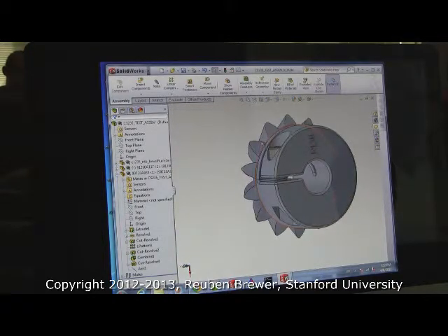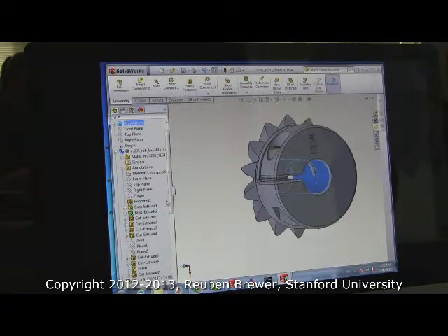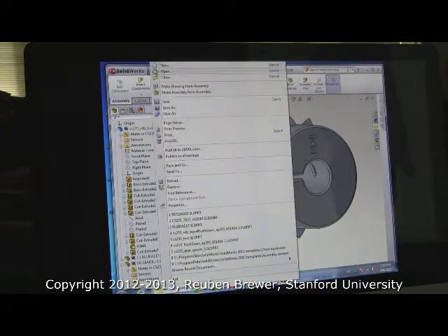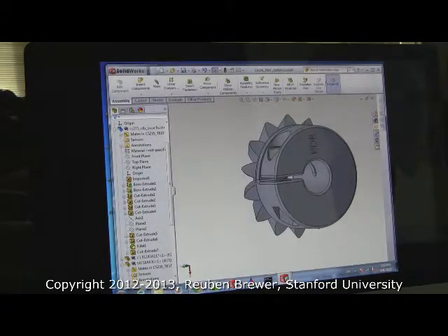We put the shaft through, and now say we want to see the axis again. We click on the gear, expand the plus sign, scroll down to that axis. So in Assemblies, depending on how yours is set up, you can view different things.